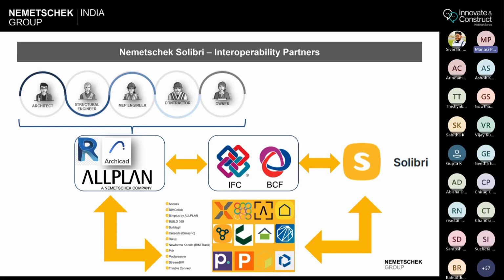So the whole workflow from any BIM authoring tool today, no matter which consultant is using which platform for a 3D model, it gets converted into an IFC, and a federated model can still come into Solibri. So what I'm saying is, if an architect is giving an ArchiCAD model, if the structural guy is giving a Revit model, the MEP guy is giving another model from some other BIM authoring tool, and all these three IFC files come into Solibri, a federated building model can still be reviewed easily, can be checked easily in Solibri through a global file format, that is IFC.